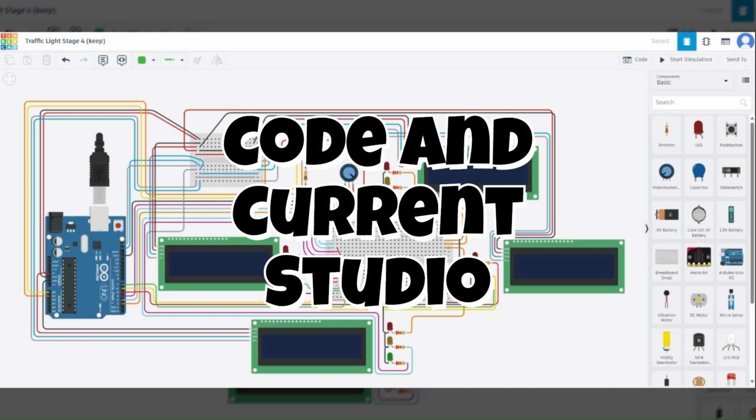Welcome back. In stage 4 of our Arduino traffic light control system project, we're adding smart traffic logic using a potentiometer to simulate traffic volume. This allows us to dynamically adjust the green light duration based on the potentiometer's position. We'll also preserve the night mode functionality from stage 3. We'll be reusing all of the components from the previous project and adding the potentiometer.